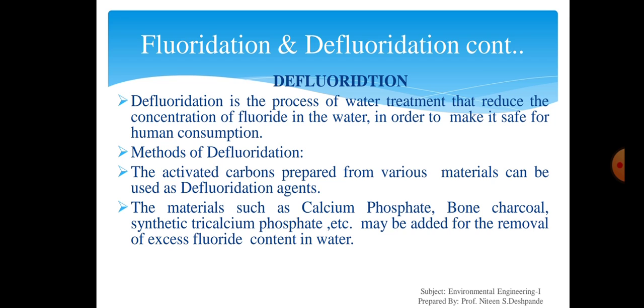Aluminum hydroxide microflocks are produced rapidly and gathered into larger, easily settling flocks. Due to that, the specific gravity of the particles increases, therefore the mixture is allowed to settle. During the flocculation process, many kinds of microparticles and negatively charged ions, including fluoride, are partially removed by electrostatic attachment to the flocks. So, this is how the Nalgonda method works for the removal of fluoride present in the water.